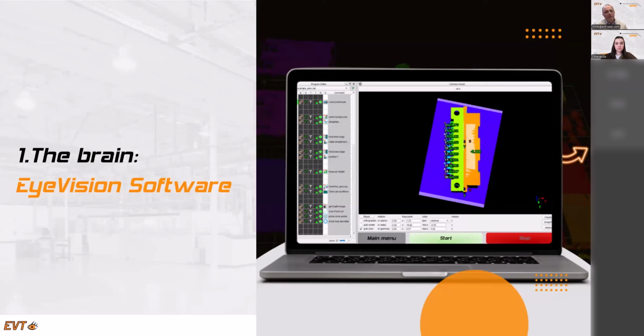And finally, if you have very high-speed systems, either you need not a gigabit Ethernet, you could use a 10 gig E. Most of the manufacturers now have 10 gig E cameras, or if it's faster, you can use PCI Express or the now more or less outdated interface, Camera Link interface. So finally, for you as a user, it's really important.